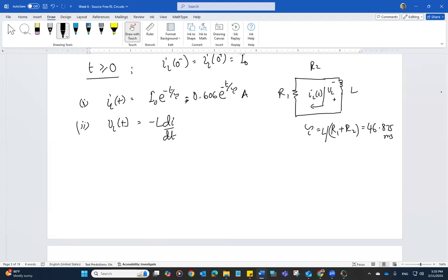So if you are trying to figure out the equation for the current, then you use negative C dV over dt if you know the voltage expression, because again, the current direction is opposite as compared to the equation that we write, iC equals C dV over dt, where iC is entering the side with the positive polarity.